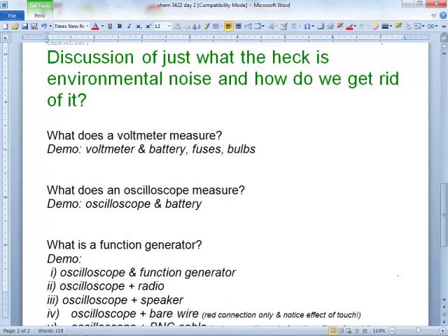Okay? So they also call this a short circuit, but there's no resistance there, essentially. It's just metal to metal. So if I do the same thing when it's wide open, circuit's broken, now it reads infinity for that thing. That's its overload. It's not even bouncing around, so it's overload. So contact, no contact.